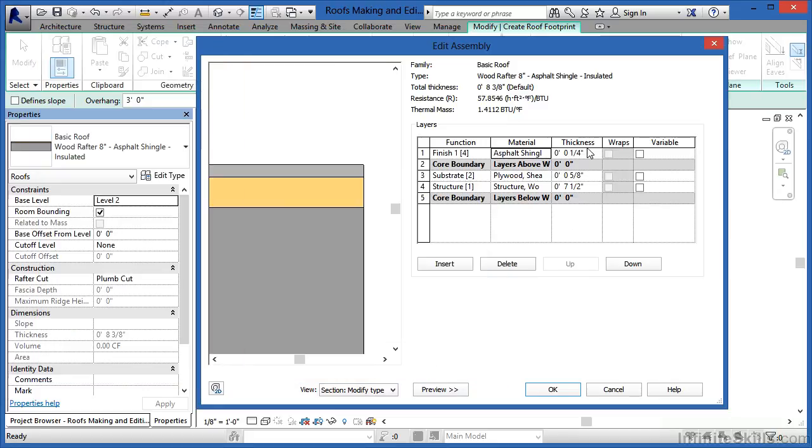Next, directly to the right of that, we have thickness. If you adjust the thickness, you'll see the thickness change of that material here in the preview, such as instead of 1/4 of an inch, maybe we want to make this a 1/2 inch. So I'm going to change that 4 to a 2. Then click somewhere down in one of these two boxes. In this case, I'm going to click right to the side of 7.5. You notice how this material is now a thicker material. We can change that back to 1/4 of an inch as well by just moving up here and clicking on 1/4 of an inch and then clicking somewhere here in the box. See how it now gets moved back?